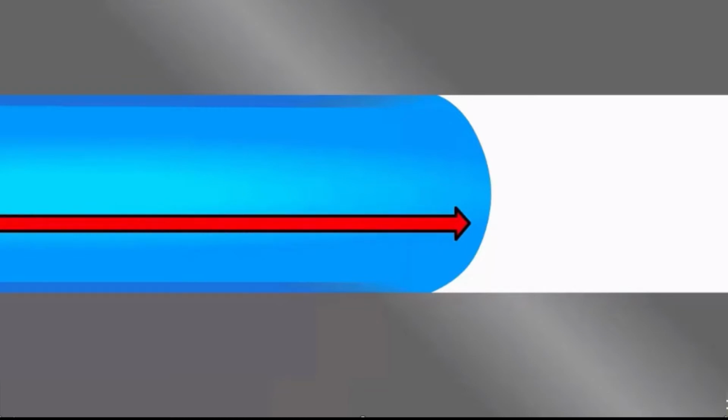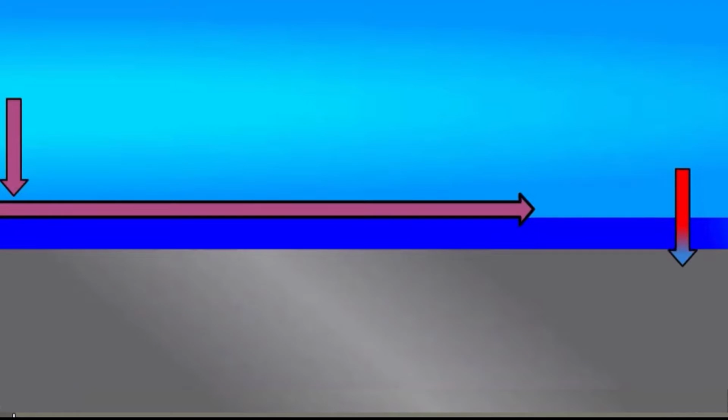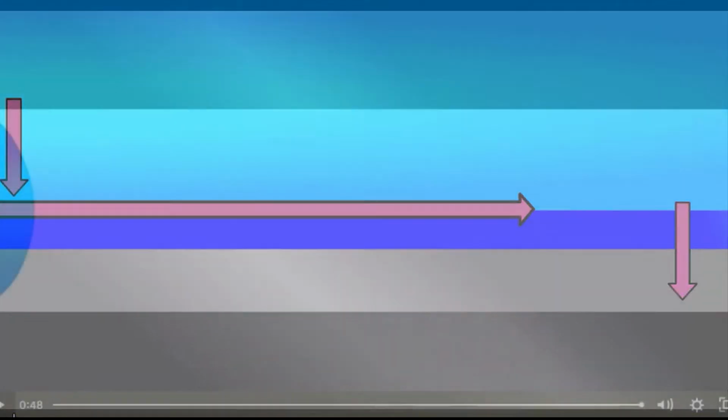As the rapidly moving core melt flows past the stationary frozen layer, the friction also generates heat. So the thickness of frozen layer increases until a thermal equilibrium is reached between the melt temperature, the frictional heat generated, and the heat loss through the frozen layer. It is important to ensure that the frozen layer in thinner sections doesn't increase too much and freeze through the thickness before the entire part is filled.